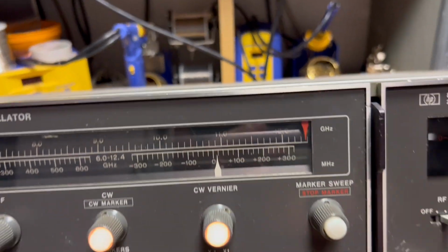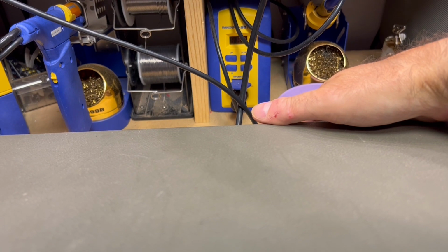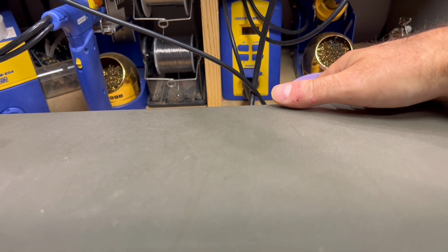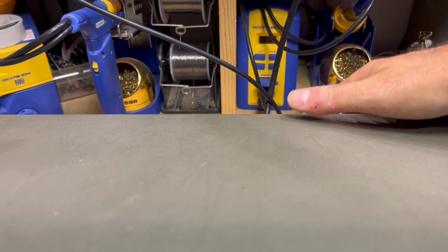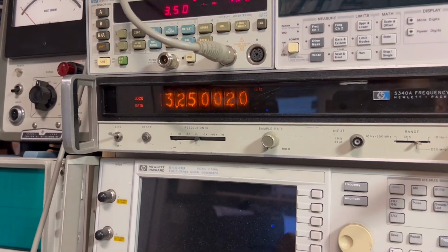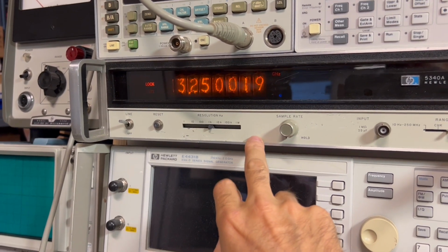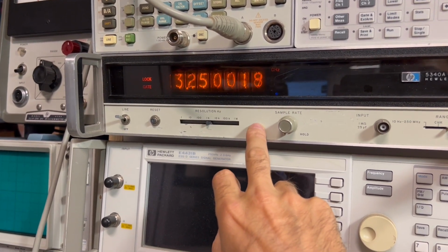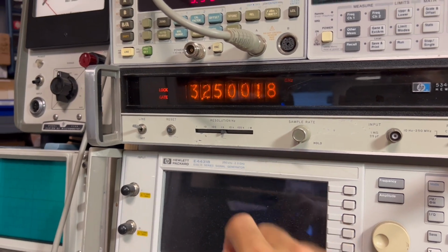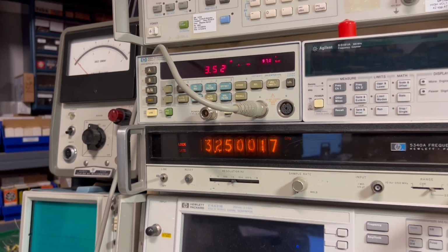And that's because we're monitoring the frequency of the signal generator using the aux out on the back, which is the base frequency of the generator before it goes through any multiplication stages. So there you go. For those last two measurements, we'll have to use this times 2 to get the actual frequency. And you can see here showing our relative measurement 3.52.